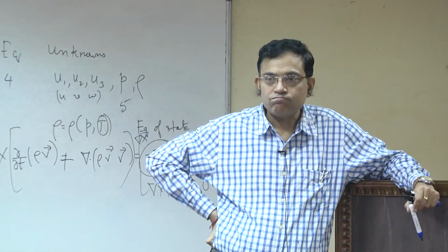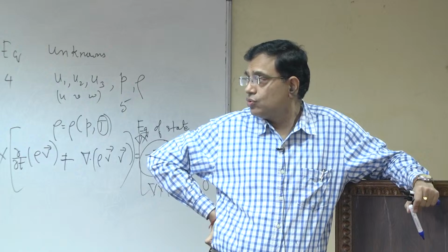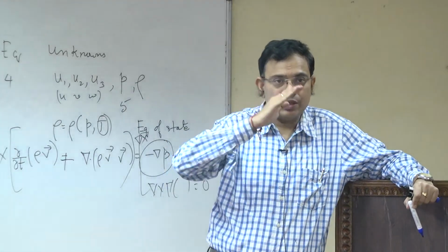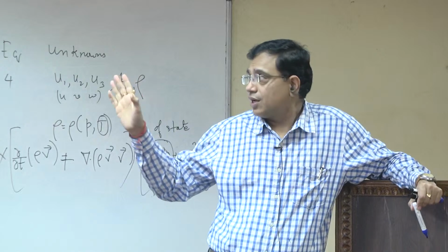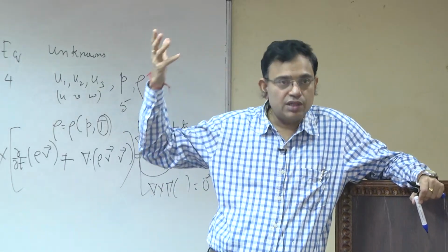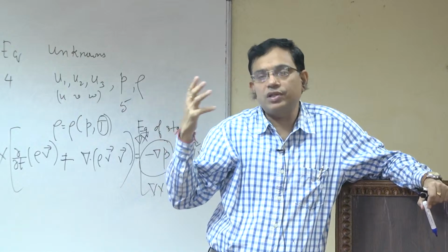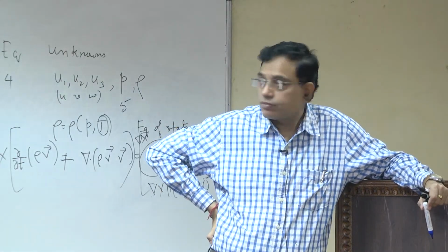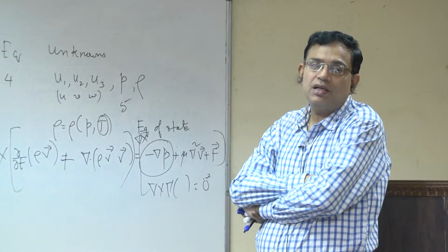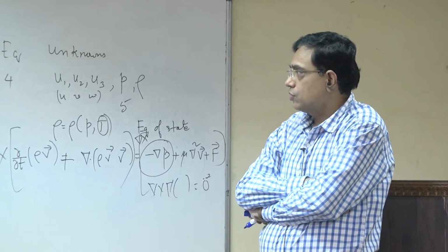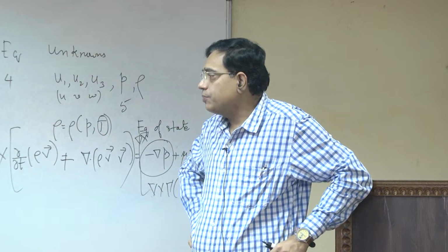But the staggering is a very important concept, because conceptually it tells how to overcome this unrealistic thing that comes in the interpolation. So, remember that the staggered grid is one way of just illustrating it, but the overall conceptual foundation of how to derive the equations does not depend on whether it is staggered or collocated grid. In the staggered grid, the benefit is that you do not have to interpolate the interfacial properties, that was the problem, and so this kind of wavy field you will not get unrealistic, and pressure is going to drive the flow,